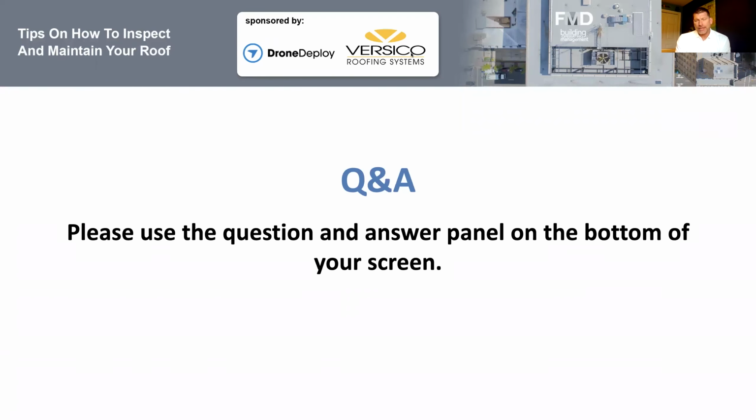Yeah. The other thing is before we go into a re-roof, if they're leaving the existing roof, we'll request that a service like Andrews comes in and does those thermal scans so that we know that we're not having our guys roof over moist or wet materials. You don't want to trap that in there before it's done. It gives you a good idea if those areas need to be cut out, or maybe the entire roof is just so saturated that it's time to come off before you can replace it.